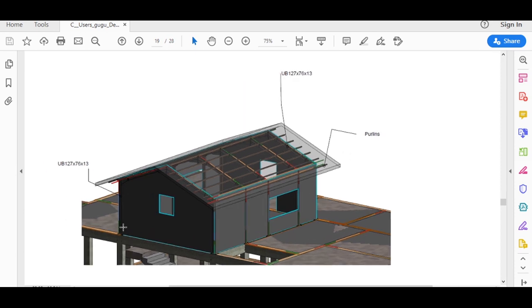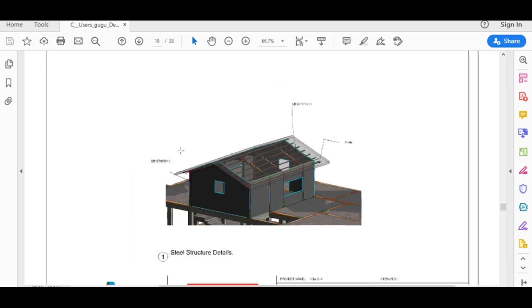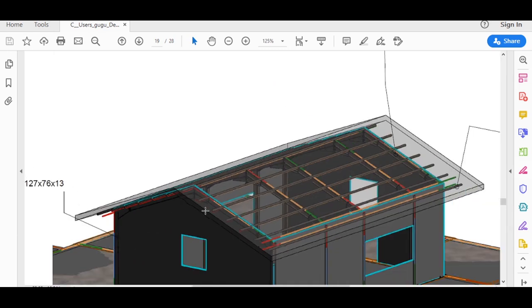Now in order to draw this wall and roof, I have used curtain wall system. I do not assign any specific material for both wall and roof. By using override graphic in view and the subject category, by category I have made transparency level to 60% for that slab, so that steel structure could be made visible for everyone who is looking at this drawing.